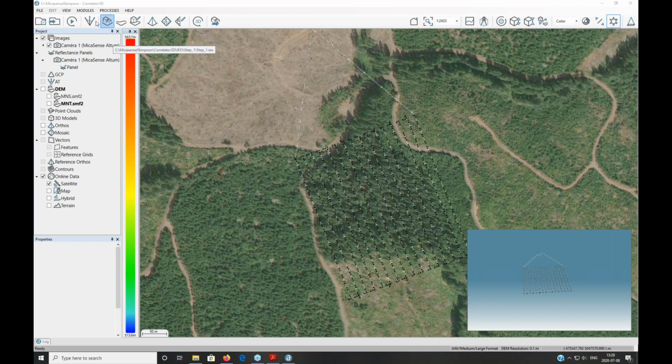So as I said, all the modules are in a sequential order. Basically, it's divided into 3 categories. The first category is the aerial triangulation, which is creating a single block of imagery, finding common tie points between all the imagery, and placing them in the right place. Once the aerial triangulation is done, the user can extract a surface model and a terrain model from the imagery, and then can perform the radiometric calibration for the orthorectification process and the creation of a seamless and color balanced mosaic.